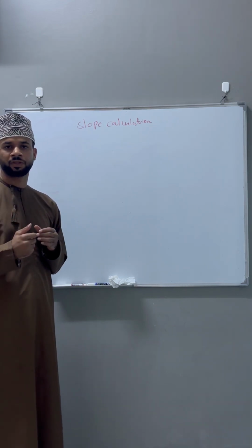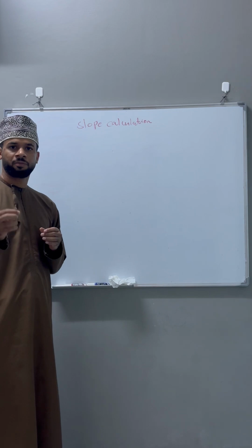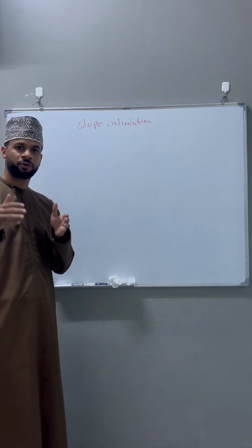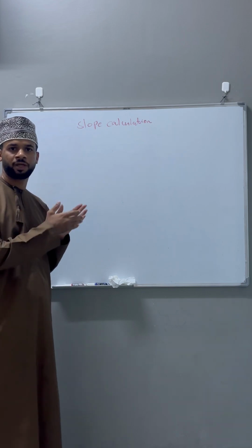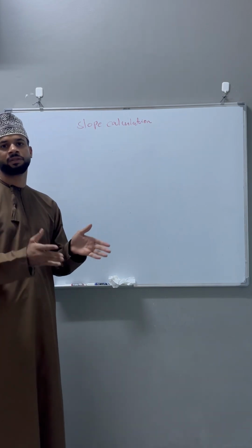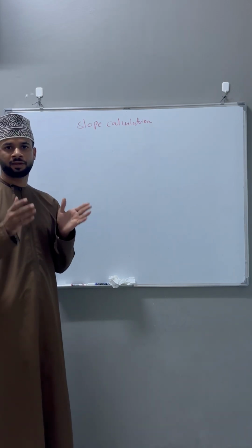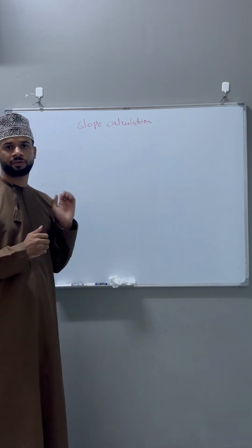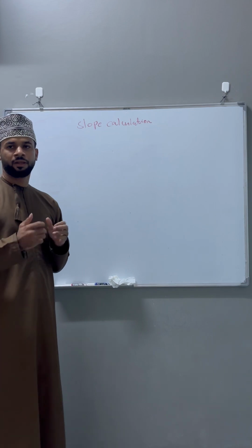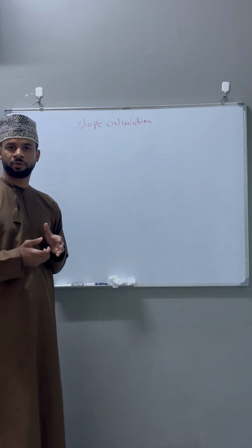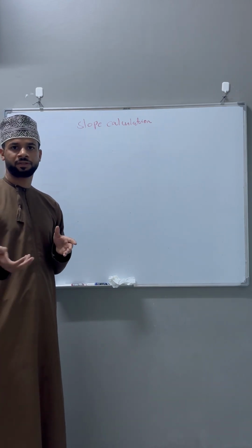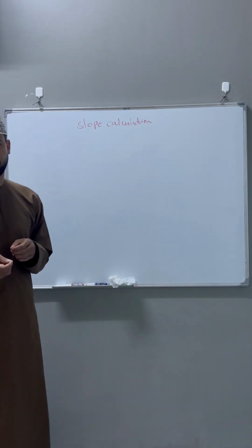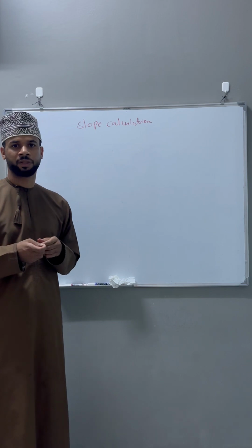Also the CT saturation. During CT saturation, no current will flow through the secondary side of the current transformer to the transformer differential relay. So 100% in that case the transformer differential relay will get some differential current, and that differential current will lead the relay to mal-operate. Then we also have the second harmonic and the fifth harmonic. These are the inrush current and overexcitation. During these cases also the transformer differential relay will get some differential current and could also mal-operate.